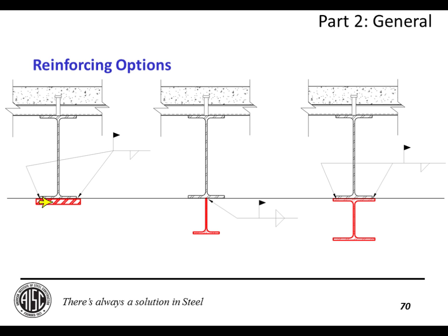There's a couple of benefits. You have downhand welds here and here. Normally a welder can accomplish a downhand weld about 4 times faster than an overhead weld. It's also nice because you can clamp this plate to the bottom section of your beam to be able to accomplish that welding. Right? So it's erector friendly. Again, the disadvantage is you don't get a whole lot of extra capacity.